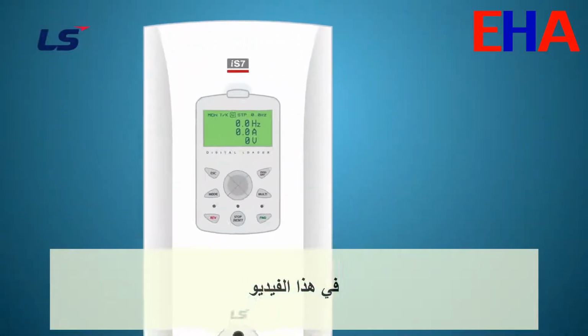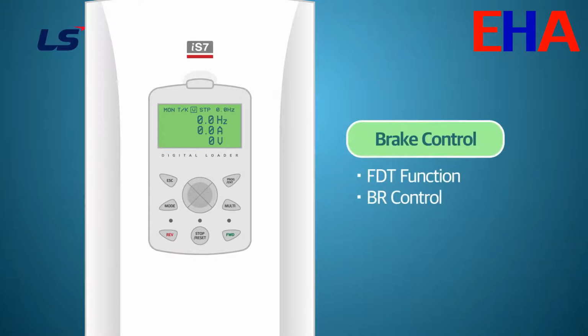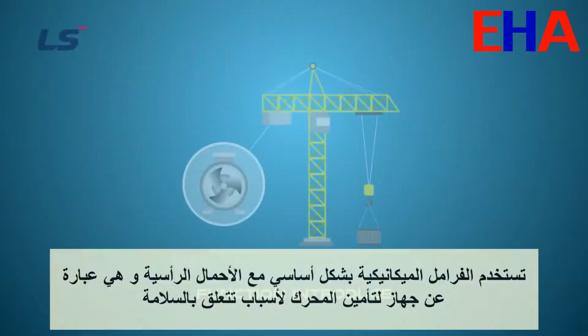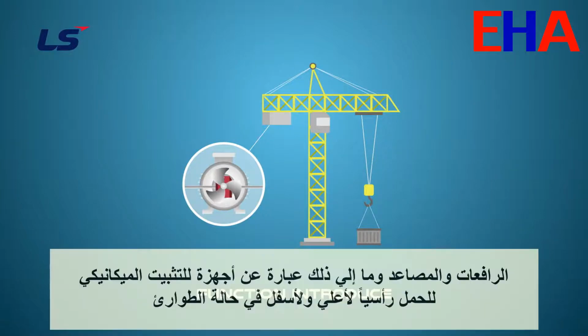In this video, we will learn about the functions of brake control on IS7. Mechanical brakes are primarily used for vertical loads and are a physical device for securing the motor for safety reasons. Cranes, lifts, etc. are devices for mechanically holding the load vertically up and down in case of an emergency.